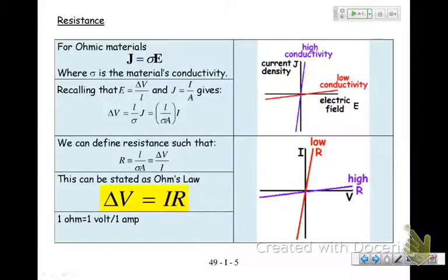So typically when we plot graphs out, we plot the independent variable along the horizontal because you're setting that. And then you plot the dependent variable, the answer, if you like, on the y-axis. And so when we plot this, I is vertical and V is horizontal, and we get a straight line. For a nice resistor, we will get a straight line. That's not always the case.